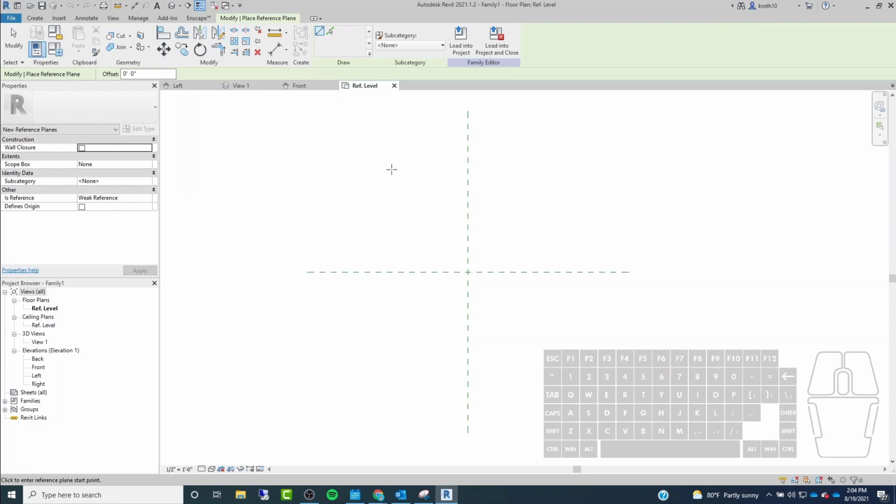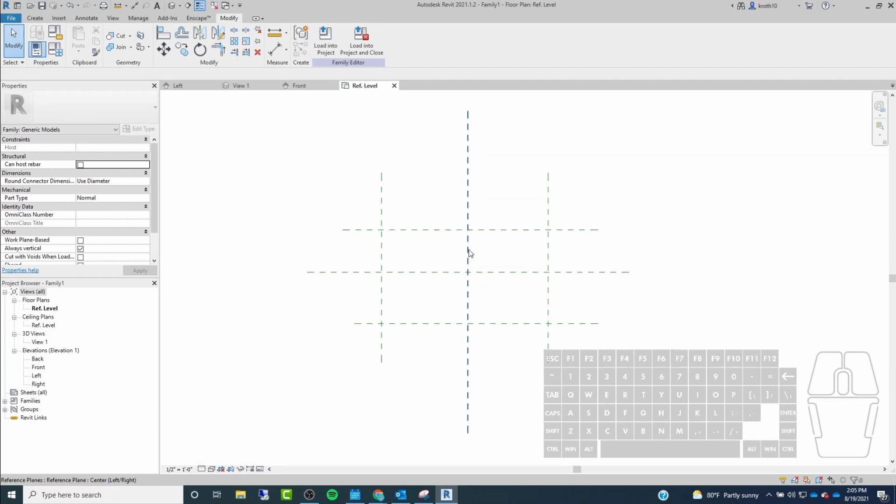Now it doesn't really matter where you place the lines. We just want them to be within these quadrants, going across either line both ways. But the length and the placement don't really matter. So for example, I'm going to start in this quadrant and draw one down to this quadrant here. I'm going to do another one over here, and then one here, and then one here. The placement doesn't matter because our constraints are going to fix it and make them all equal.